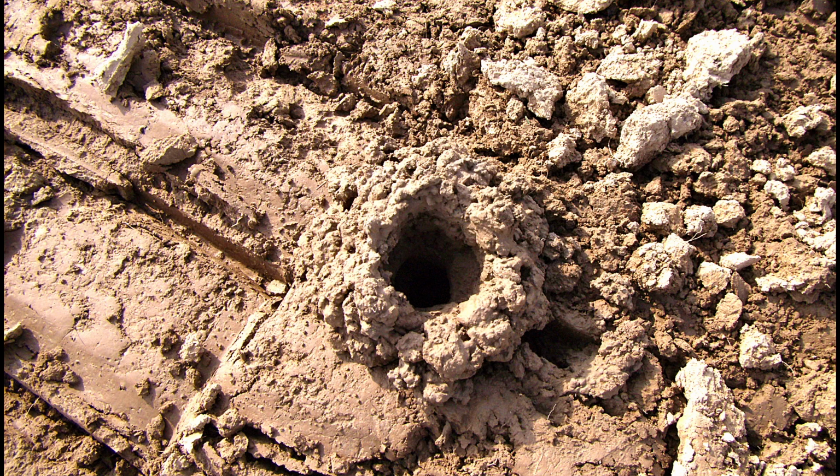You're looking at the bottom of a core trench that was dug and left open overnight. A crayfish has opened its burrow that was blocked by the dozer digging the day before. It's necessary to dig the core trench much deeper to the bottom of the crayfish holes and then to fill the trench with clay that's compacted in layers if we want the wetland to hold water.